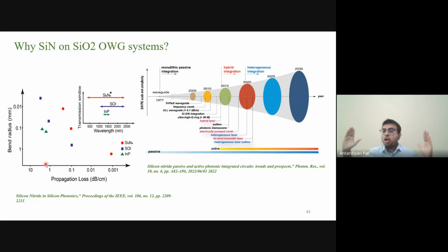That means all wavelengths starting from, let's say, 300 nanometer. I'm just quoting a number, don't take my words on this, I forgot the numbers. It allows wavelengths from as low as 300 nanometers to pass, as well as high as 1 micrometer. That means it has a huge optical window, silicon nitride. So that's why you use silicon nitride.